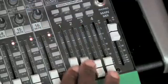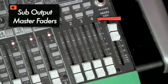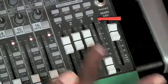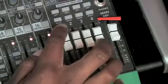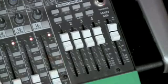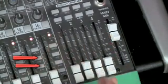Starting at the very bottom of the master section, we have our sub-out masters. These are the master fader controls for your sub-outputs. As you can see, 1, 2, 3, and 4, coinciding with 1 and 2, and 3 and 4. These are found on each of our channels. To send a signal to your DAW, as I mentioned earlier, you'd simply activate your bus assignments and use this fader to control the level going into the DAW.